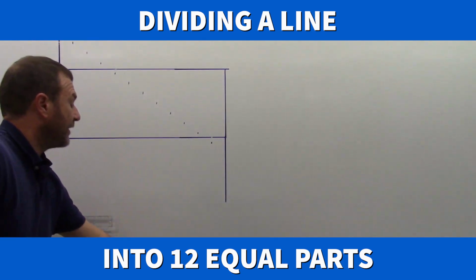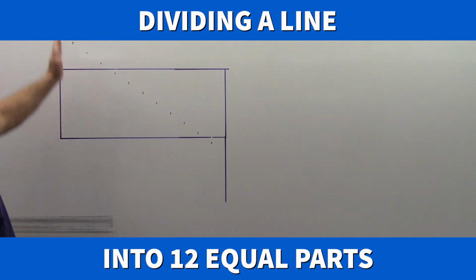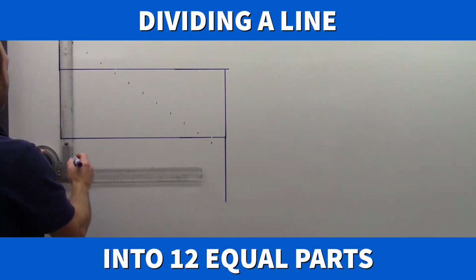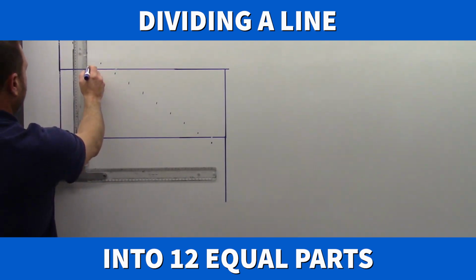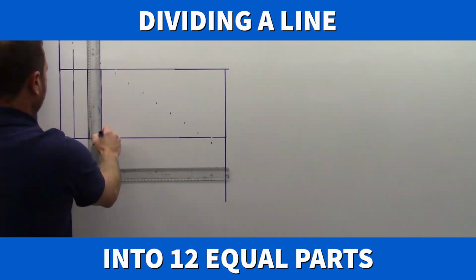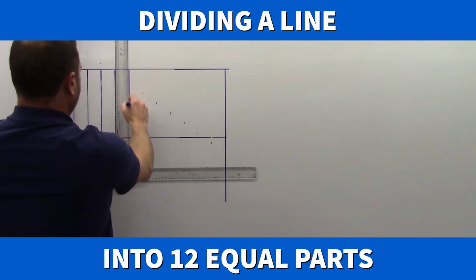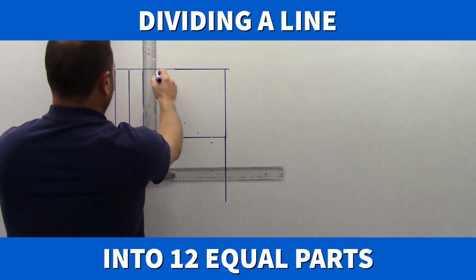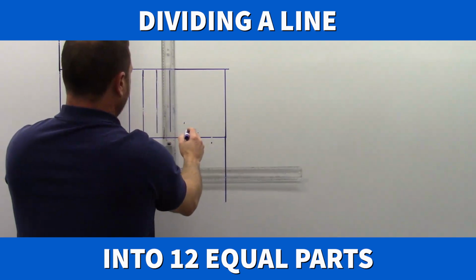And I put a tick at each spot on the ruler at 2.5 inches. And I always keep my lines vertical when I do that. You don't want your check mark coming out crooked. And now I can just square all those lines up. Each of the spaces are exactly equal.